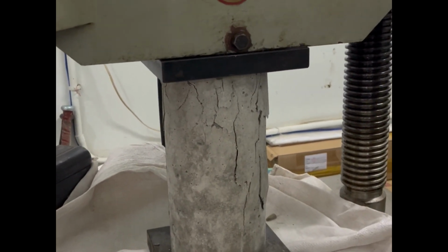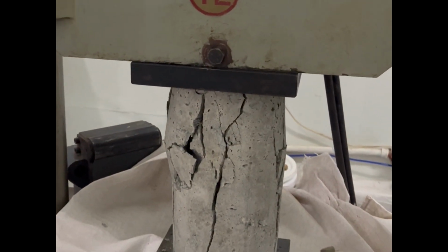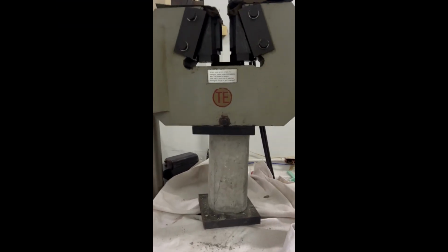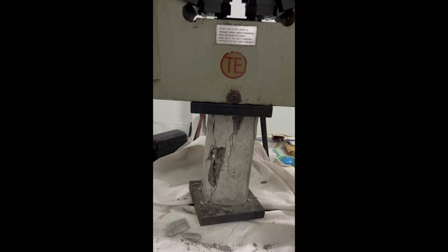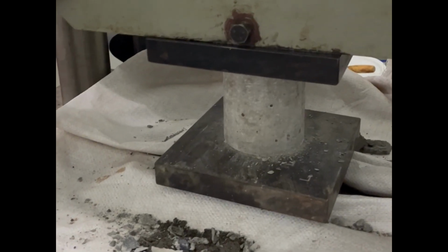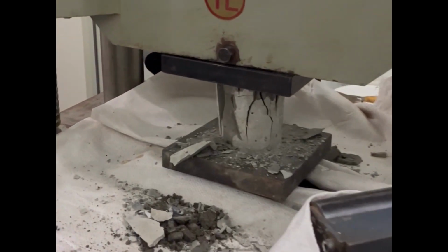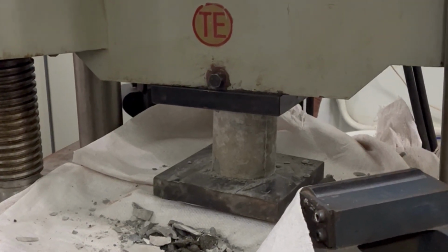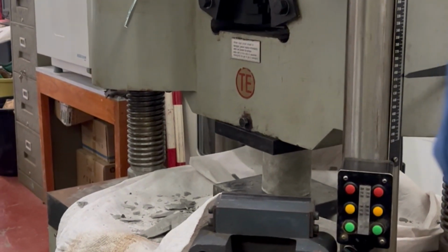The compressive strengths of mortars were determined at 7 days of age after wet curing. Here, the compressive strength of mortars and cement paste is determined by applying continuous load over the specimen until failure occurs. The test is conducted on a universal testing machine. Using the universal testing machine, we were able to come up with the following test results, showing the mortars and cement paste with their respective maximum load sustained in kilonewtons.